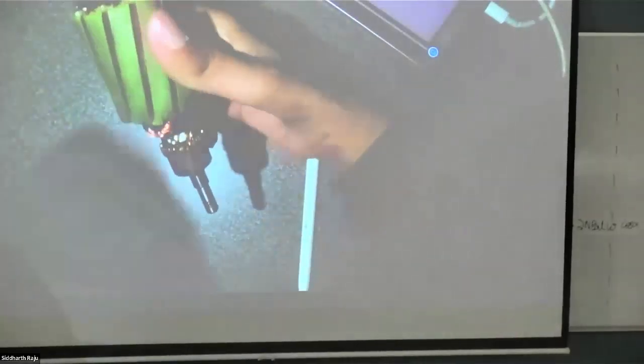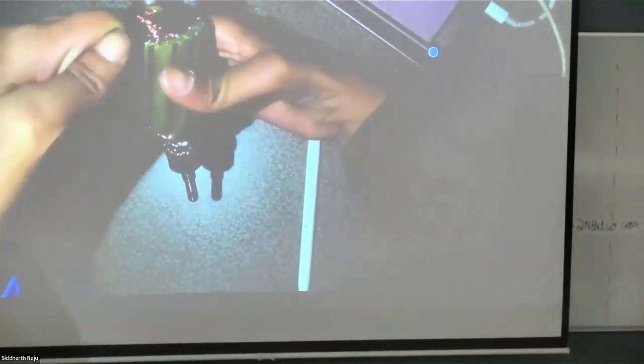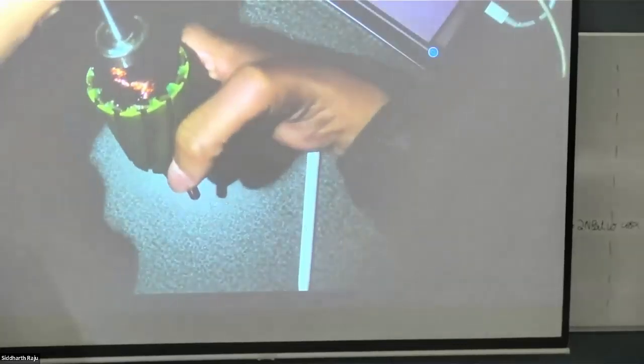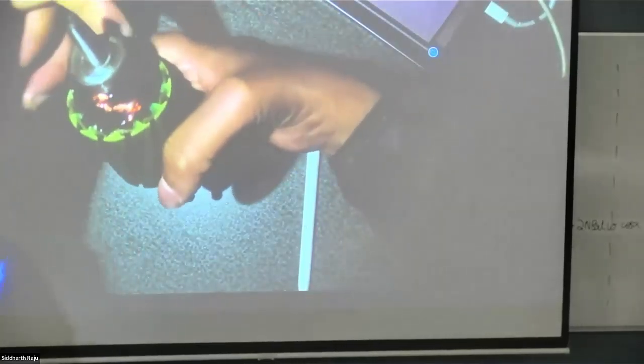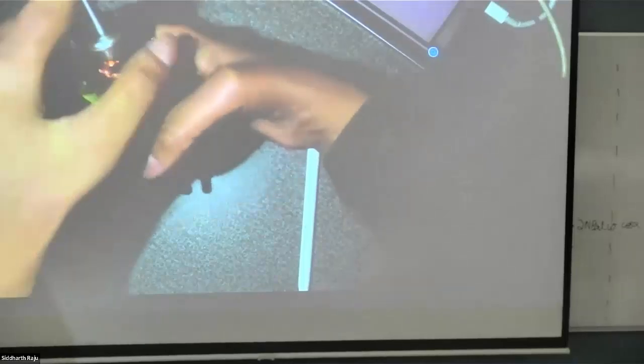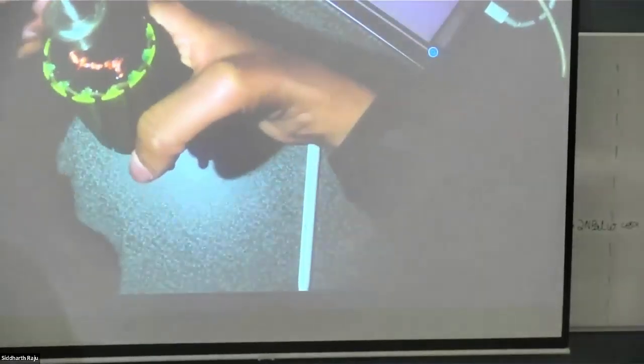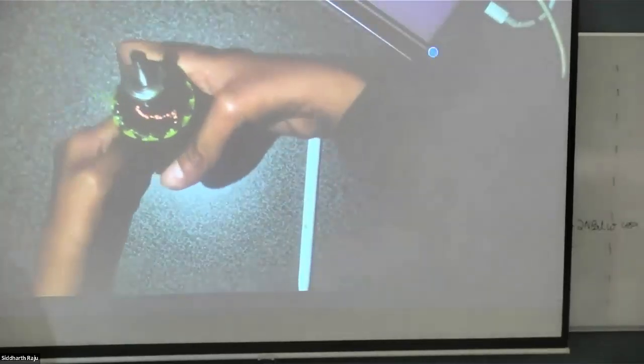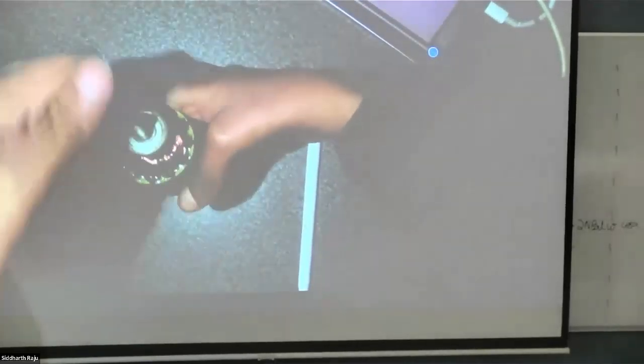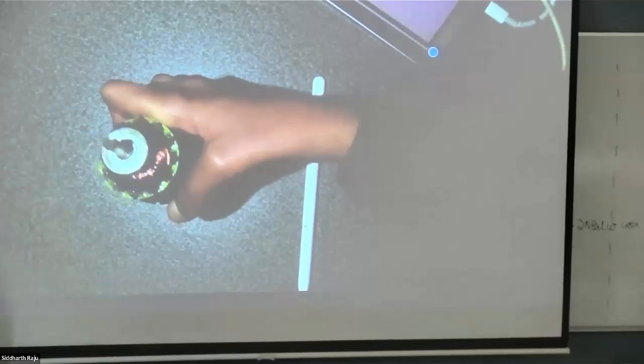And then what we do is we start off with, say, a first winding. I take a first wire, put it in this one slot, take it 180 degrees back, which is called a full pitch. You can go even a little bit lower angle too, which we'll consider later. But for now, we're going to assume we start in slot 1. We go all the way back, close one winding, bring it down, and do this n number of times. That was the n that I wrote there in our equation for one loop.